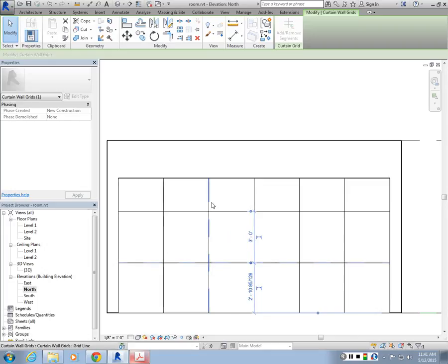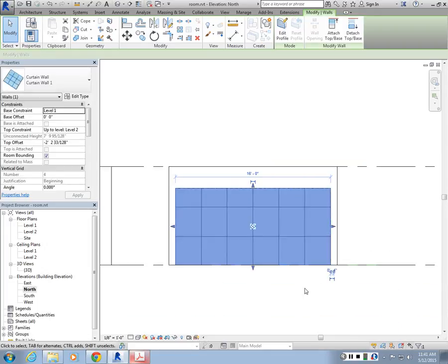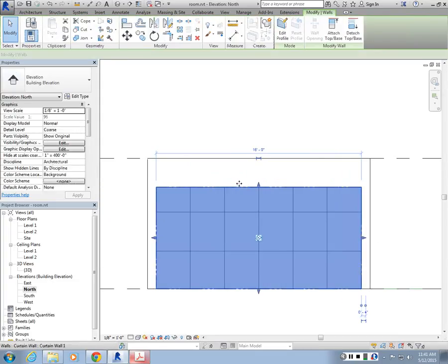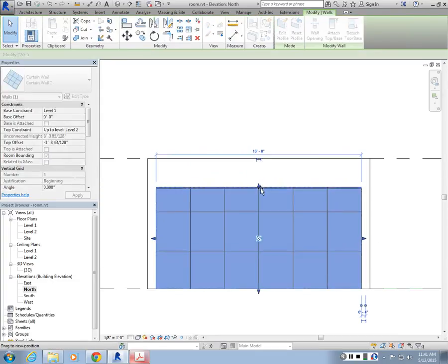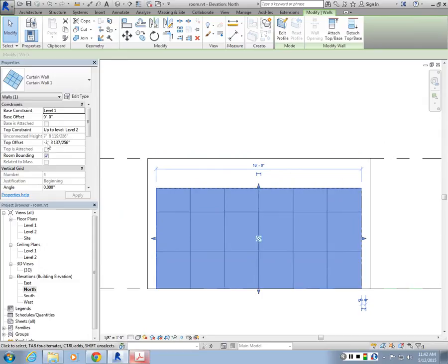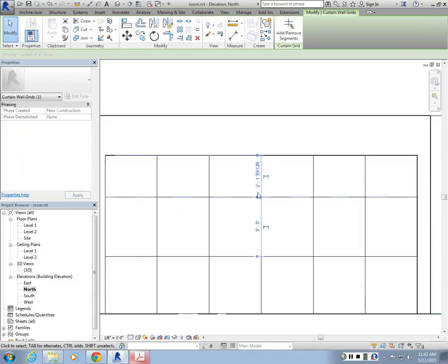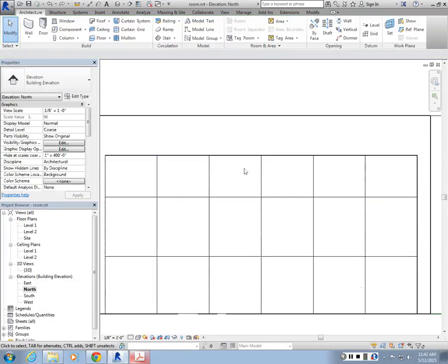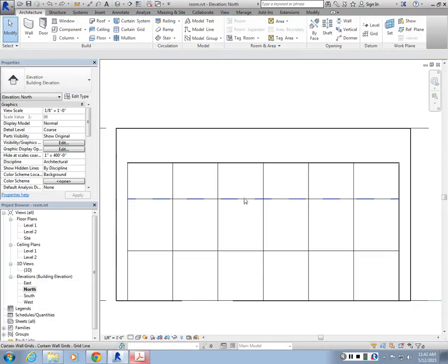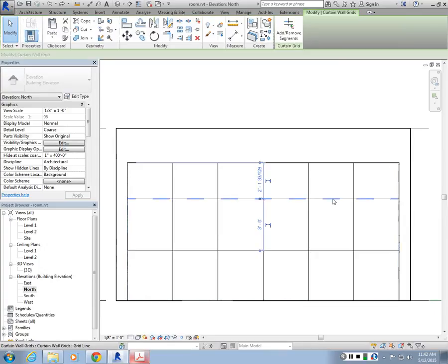This one 3 feet as well, and this one I don't have a perfect value. It's because I think my top offset is not perfect either. So I'm going to make it -2 feet. Hit apply. Now this guy is 3 feet. Let's make this one, well, let's keep it at 3, and whatever we left over is left over. Now I got a basic division.